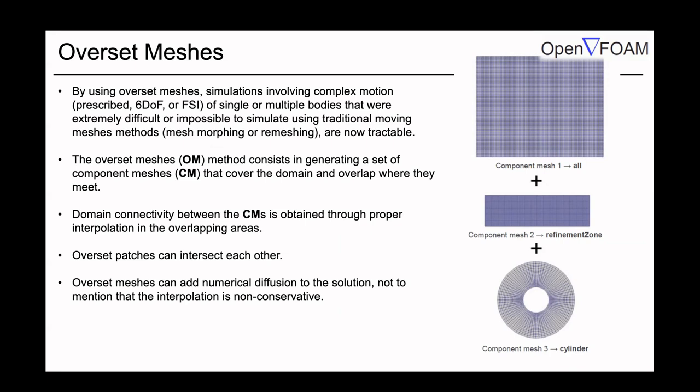Now, the boundary of this mesh will be called an overset boundary and will also be used as a boundary condition. And also in the second component, the boundary mesh equally will be overset. So these boundaries where interpolation actually happens from one component to the other have to have cells of the same size. So that is one way to reduce the interpolation errors, and it's very intuitive, right?